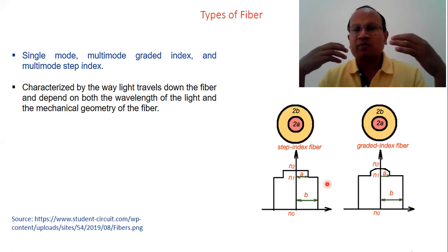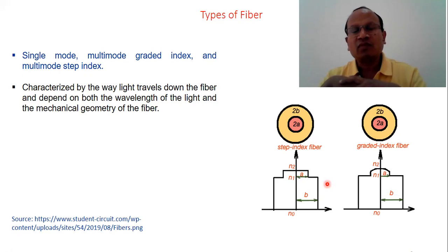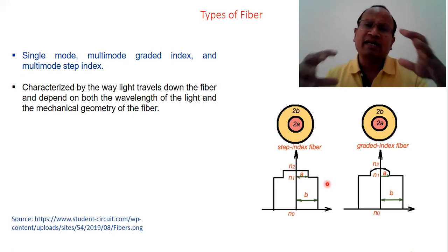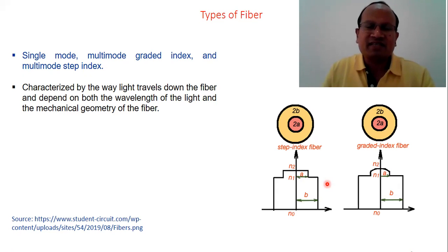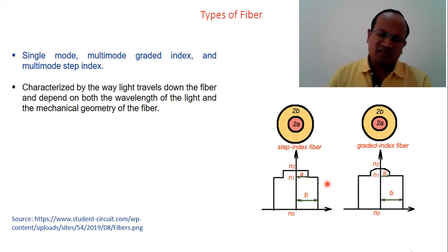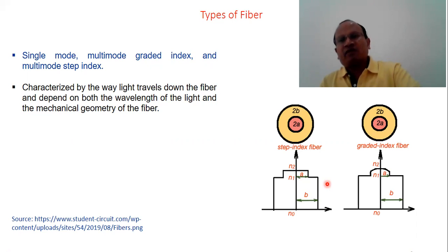There will be a refractive index profile of both regions. And how does that grade? Grading means how it changes. That grading profile means it's not a pure material, it has been constructed as a specific material, although the core is always supposed to be of pure silica or pure glass material.